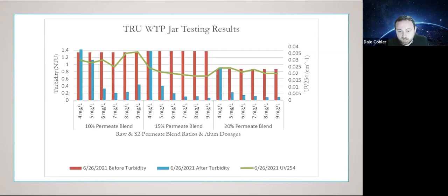Additionally, alum is an acid with a pH around 3.5, which will lower the pH of that blended sample, which is usually between 7 and 7.3. The pH range of the water is important to the efficiency of the coagulation.